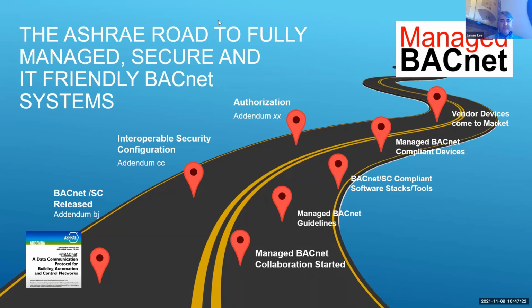Yeah, we'll start with MSTP. No, there are no certificates required for MSTP. The certificates only apply to BACNET Secure Connect. And that's because the certificates are using TLS, and TLS is a technology that is only used on IP networks.